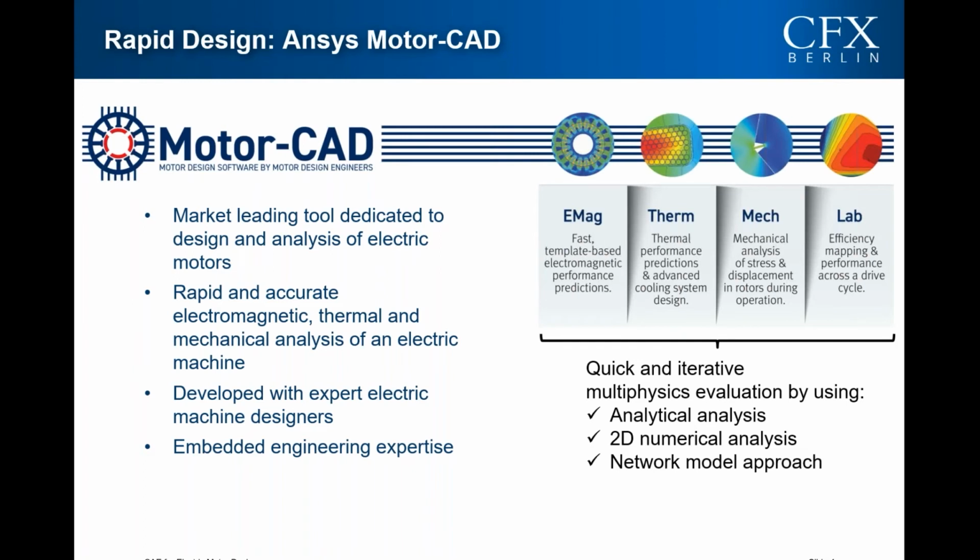We have 4 design modules in MotorCAD. The EMAG module that allows the evaluation of electromagnetic performance based on predefined motor templates. The powerful therm module to predict thermal performance, like winding and magnet temperature, based on predefined cooling templates.